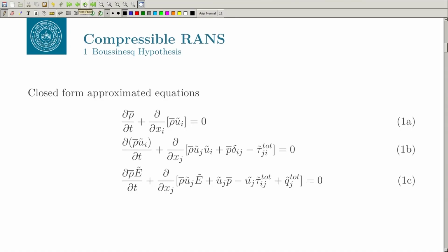Hello everyone, welcome back. We have been discussing turbulent flows. We looked at the RANS equations for incompressible flow and compressible flow, and we also started discussing how to address the closure problem in turbulent flows. So, the Reynolds stress that we get, how do we model it? We looked at Boussinesq's hypothesis briefly in the last class, and we will elaborate it for all three dimensions in the present class, and then go to deriving turbulence models.